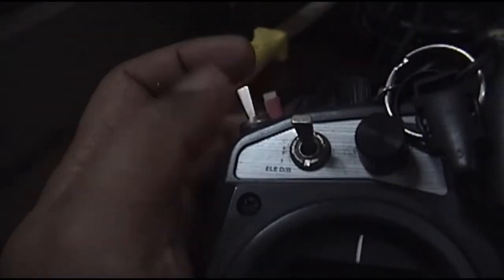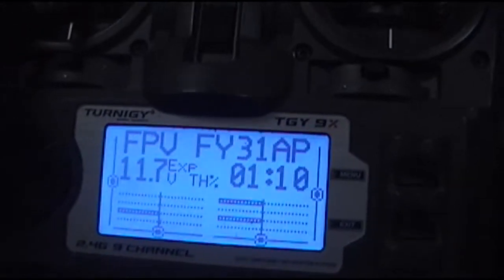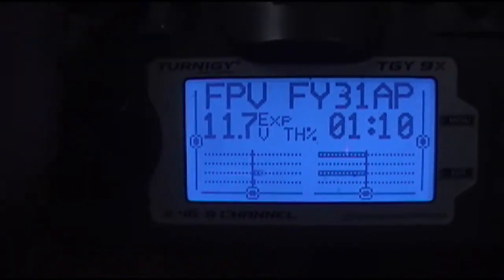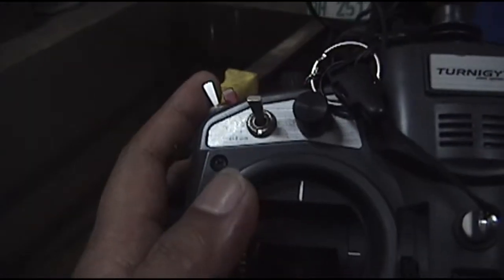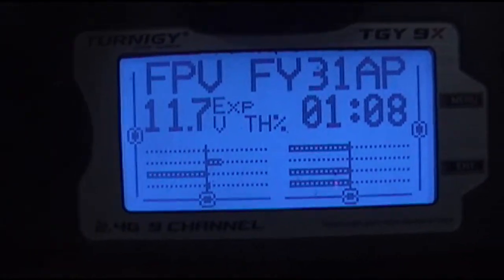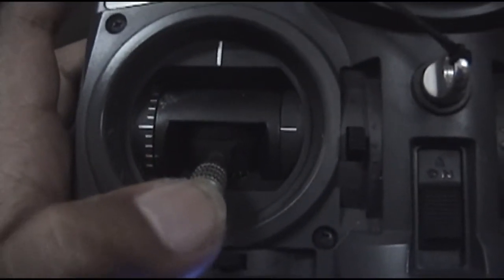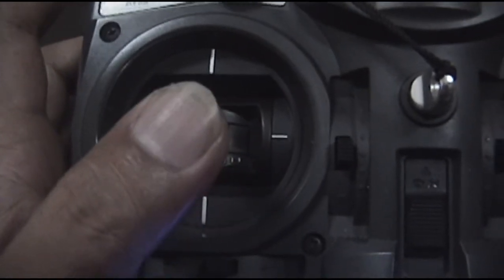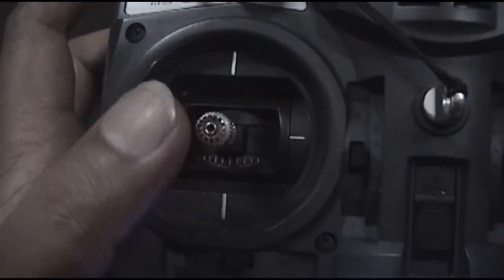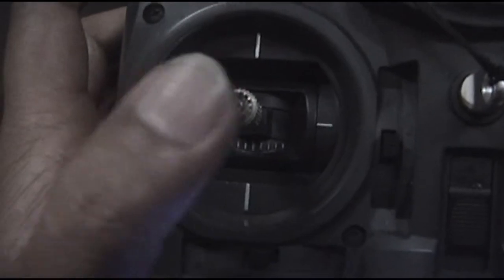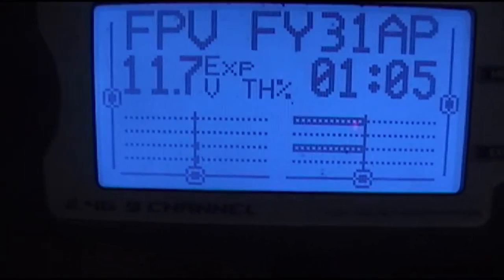When the switch is off, the one that I made master, everything is normal. No flaps, no nothing. And when I turn the switch on, it activates the flaps. And the flaps depends on the amount of stick input. From mid stick, that is 0, there's no flaps.